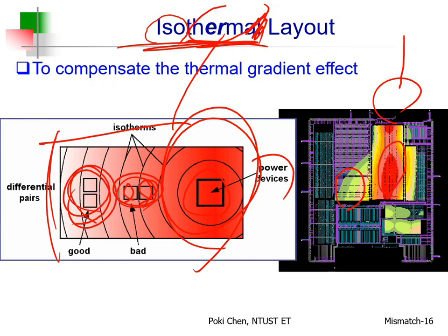Anyway, I don't think during your layout you will know where that is. You won't know the exact thermal distribution of the whole chip, right? Unless you have such kind of EDA tools, otherwise you don't have the whole picture. So my recommendation is at least you know who will consume the most power. Your power MOSFETs, and so on. Okay? During layout, you will know which part of the circuit will consume more power than the others.